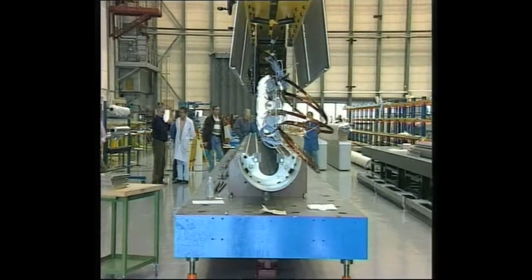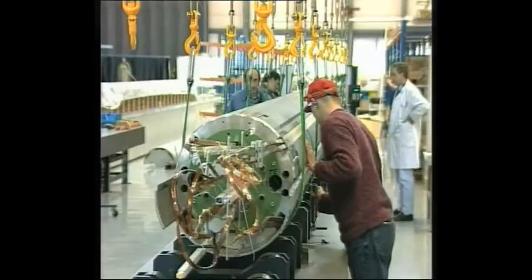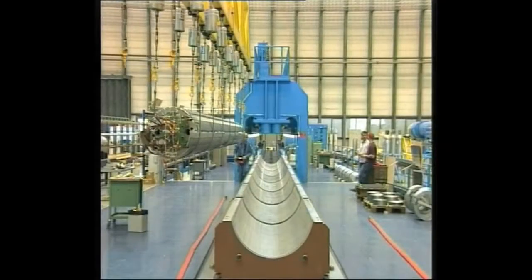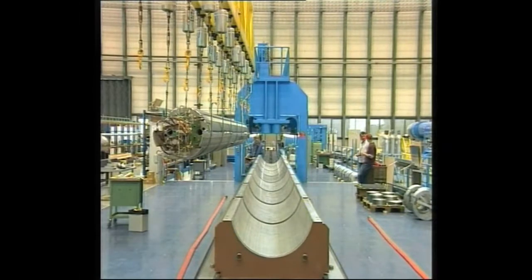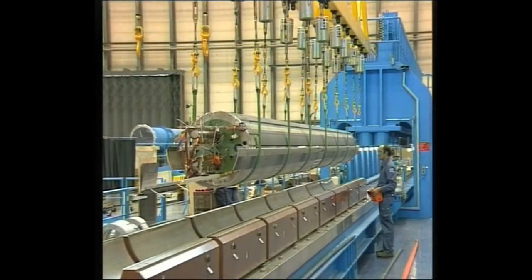In the assembly hall, a complete magnet with its tightening collars is placed in the yoke. Once assembled, the dipole will be introduced into a giant press in order to compress the elements and weld them. This press, which exerts a pressure of 900 tons per meter, has another function, slightly bending the dipole to give it a shape compatible with that of the circular tunnel.